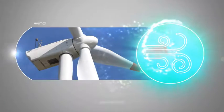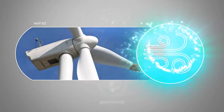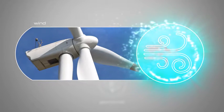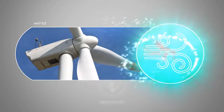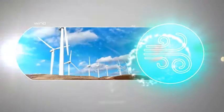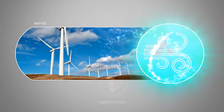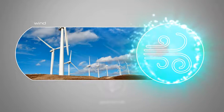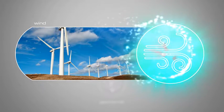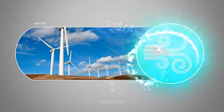The horizontal axis wind turbine has a main rotor shaft and electrical generator at the top of a tower and must be pointed into the wind. This is typically achieved by use of a wind sensor and servo motor. Large horizontal axis wind turbines have variable pitch blades that can change the pitch of the blades to control the rotation speed of the rotor shaft. Turbines used in wind farms for commercial production of electric power are usually upwind three-bladed turbines.